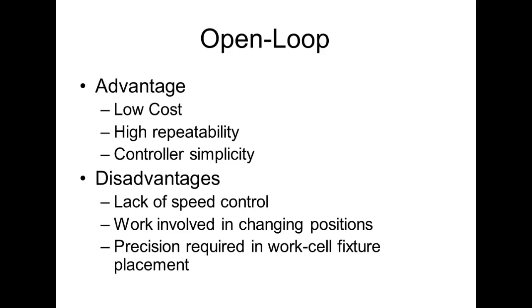If I'm going to run an open loop system, and the robot is closed loop, and it's going to swing over here and pick something up, well, if it's open loop, then this guy down here has got to be in a perfect position for it to pick it up, right? You understand? Yes or no? We'll go over there and look at the line and look at some of those jigs where parts fall into a certain position. All the robot knows is to go to that position, and it's depending on that device to be at that place.